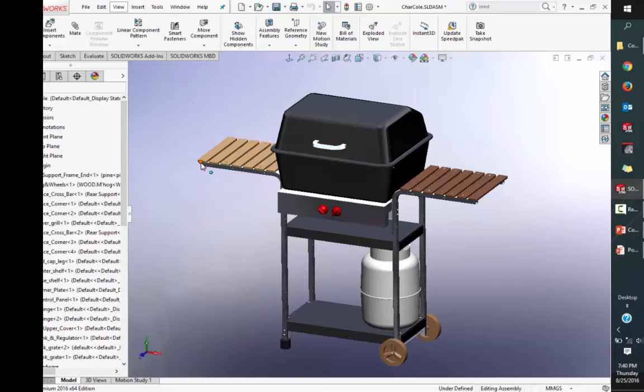When you use configurations, your controls are purely at the level that you're using it at. If you're using a configuration in a part, you're only going to control stuff in a part. If you're using configurations in assembly, you're managing features and dimensions, suppression states of only assembly features. A part is an assembly feature, but the feature in the part is not in that realm. Okay, so I can suppress a part, I can modify a dimension that's in a mate, but I can't modify a dimension that's in a part. So it kind of gives you that hierarchy thing.